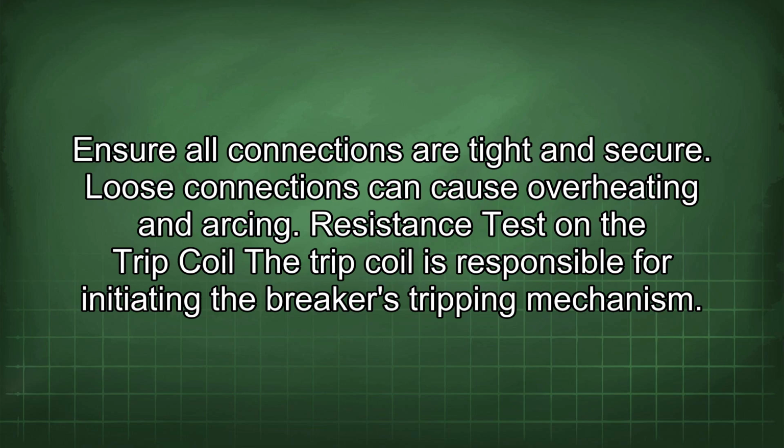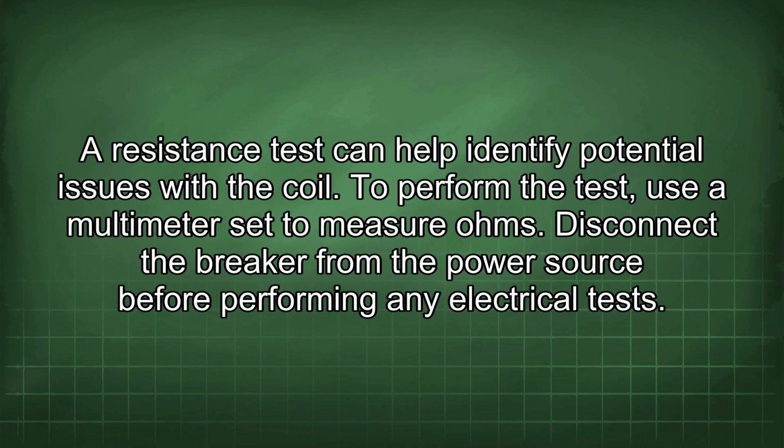Resistance test on the trip coil. The trip coil is responsible for initiating the breaker's tripping mechanism. A resistance test can help identify potential issues with the coil. To perform the test, use a multimeter set to measure ohms.